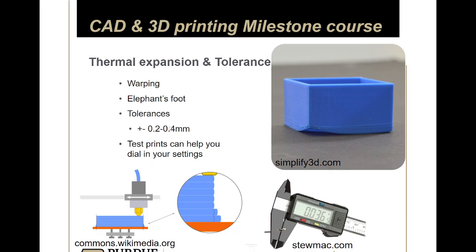Okay, so this is a little bit more of a nitty-gritty kind of thing, and I think it pertains more to people who use the 3D printer, but you can mitigate some of these issues in your design. When you 3D print certain objects, or just every object, you're heating up a material and then you're cooling it down. And when you heat cycle that material, it'll expand and contract. And depending on your model or the material, those contractions can impact the physical model itself, right?